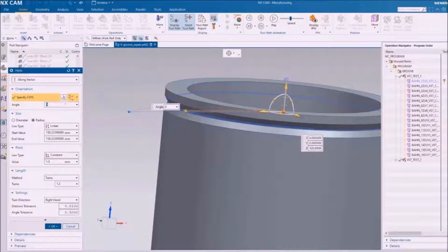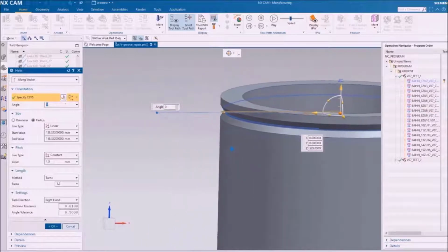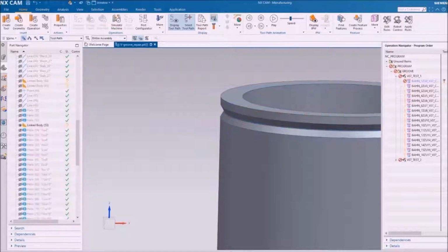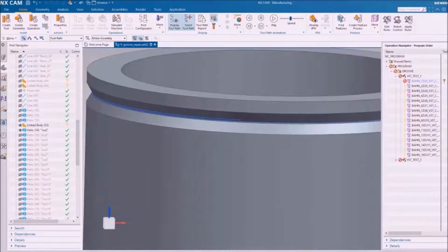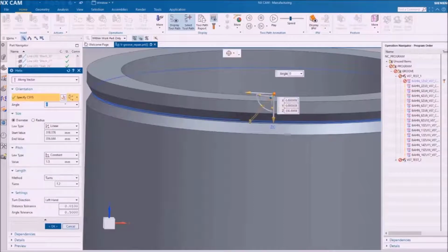A spiral movement of the cold spray nozzle around the cylindric component presents a suitable driving strategy. The starting point for the repair process is placed in the center of the groove because they are the steepest and requires the most material, that is, the most repetitions of the deposition path. Starting from this point, the tool is moved on a helix-shaped path.